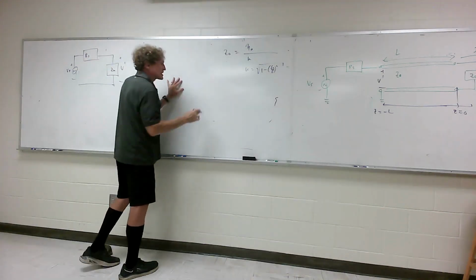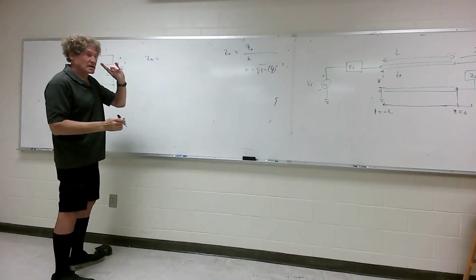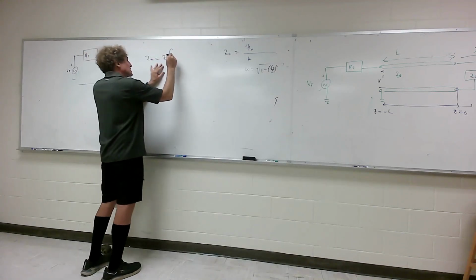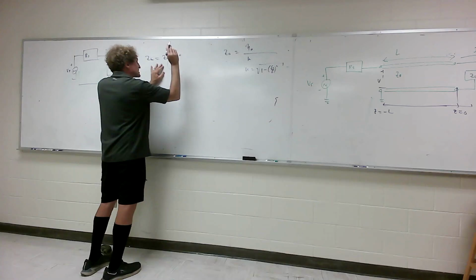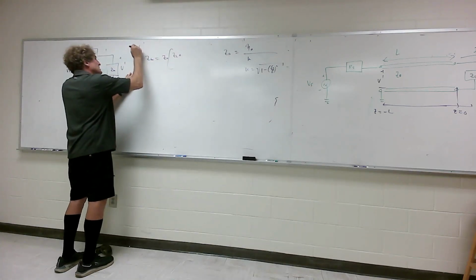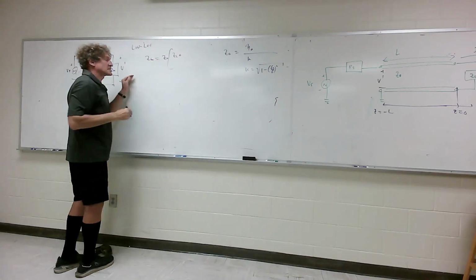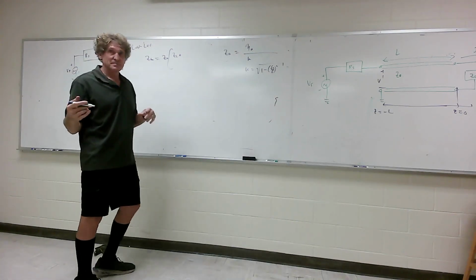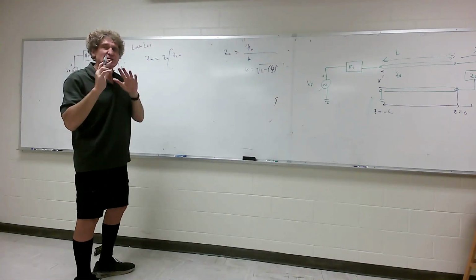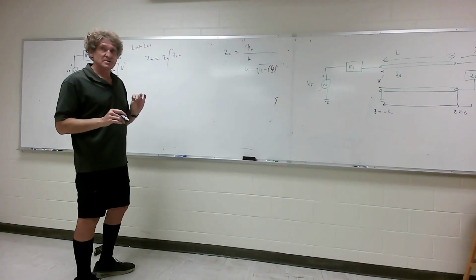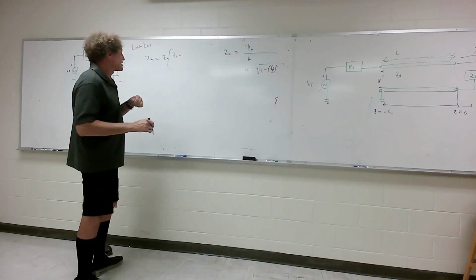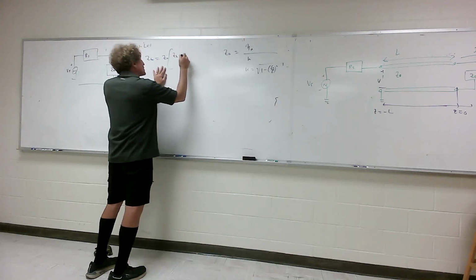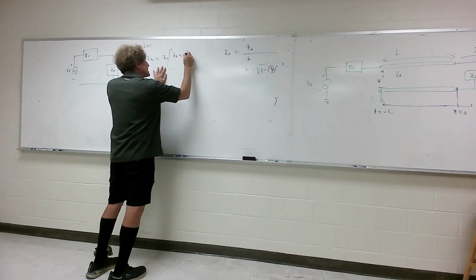So I'm going to use this Z naught as the characteristic impedance of the guide in the equation. So it's going to be Z naught times ZL plus, and by the way, we're assuming no losses. It doesn't make much sense to have a lossy guide. Why are you using it? I mean, that's the first logical question. There's very low loss, but you don't need to consider it in this input impedance formula. We can deal with that later. So it's going to be ZL, the impedance of the load, plus j Z naught.